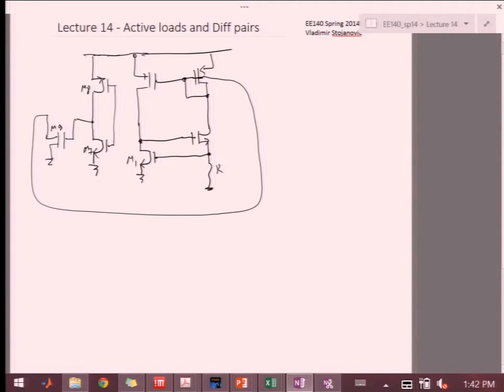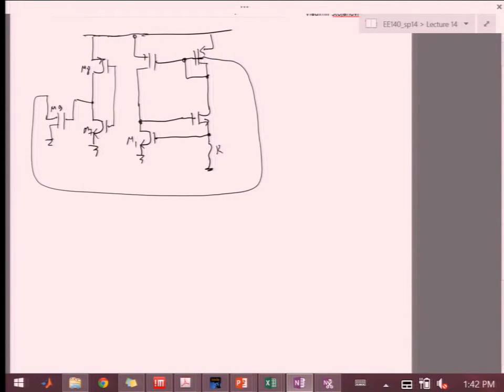So what's happening here is that in my initial state, let's say I end up in this state where there's no current flowing, right? So there's no current flowing through this resistor. Oh, sorry. This voltage, which is across the resistor, is driving the gate. So if there is no current, then this voltage here is 0.